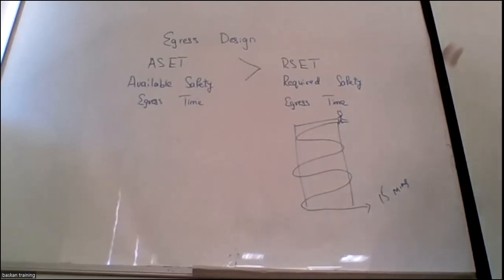Because 2 hours of fire resistivity of horizontal exit means your doors, your walls, your horizontal exits, any type of corridor, should have 2 hours, because usually the evacuation time that is considered is 1 hour for the people in a mid-rise building. In high-rise buildings, it could be more than 1 hour. So when the evacuation time is more than 1 hour, for the horizontal exits you will see 3 hours to 4 hours. So there are different parameters, but all in all, they come together towards the egress design, because you want to provide a safe pathway for the people to evacuate.